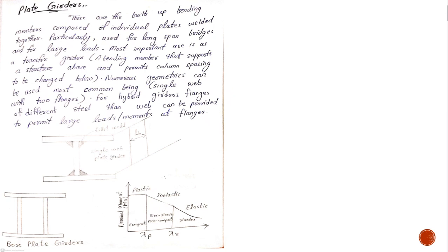In the previous lecture, I told you that very long flanges are supported by these deep stems or web, and as it is very long in this direction, we require some lateral stiffness because we have to prevent lateral buckling. So buckling requirements are also taken into account while designing these.